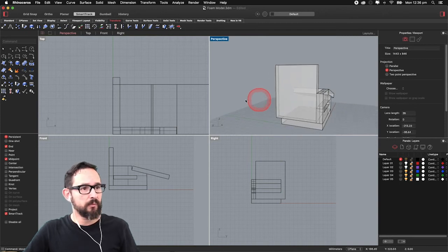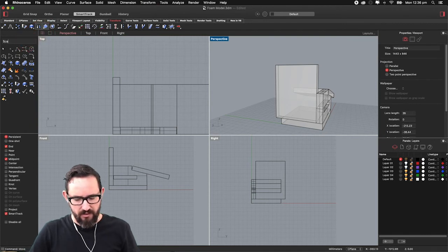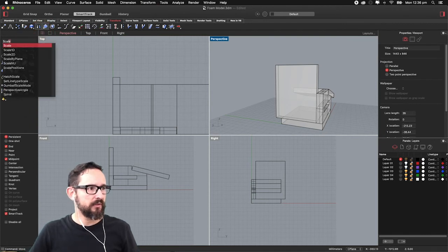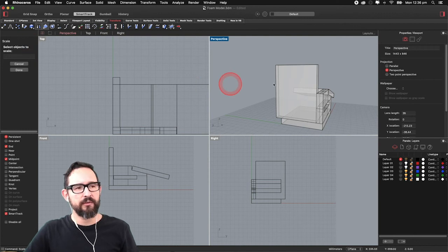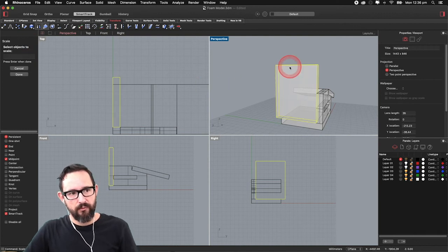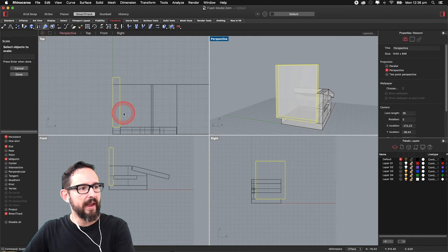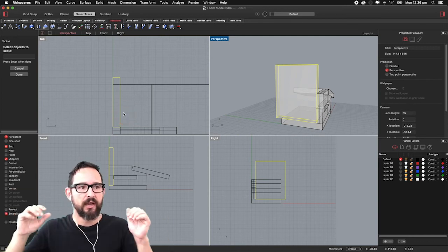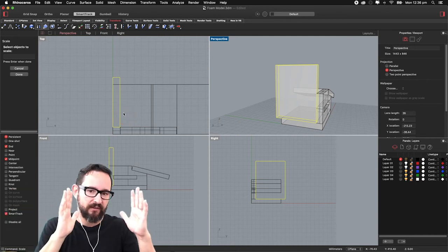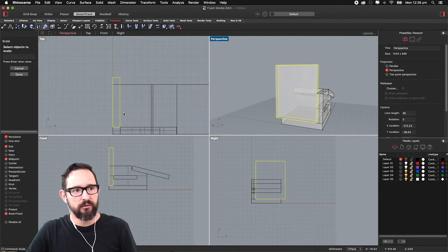For that I'm going to use another transform tool, which is the scale, and the scale is this one, which is always in the transform tools. But in scale, there are a few things that I would like to tell you. If you choose just scale, everything will shrink. Actually, I just want to shrink one side. So that's what we need to look into.